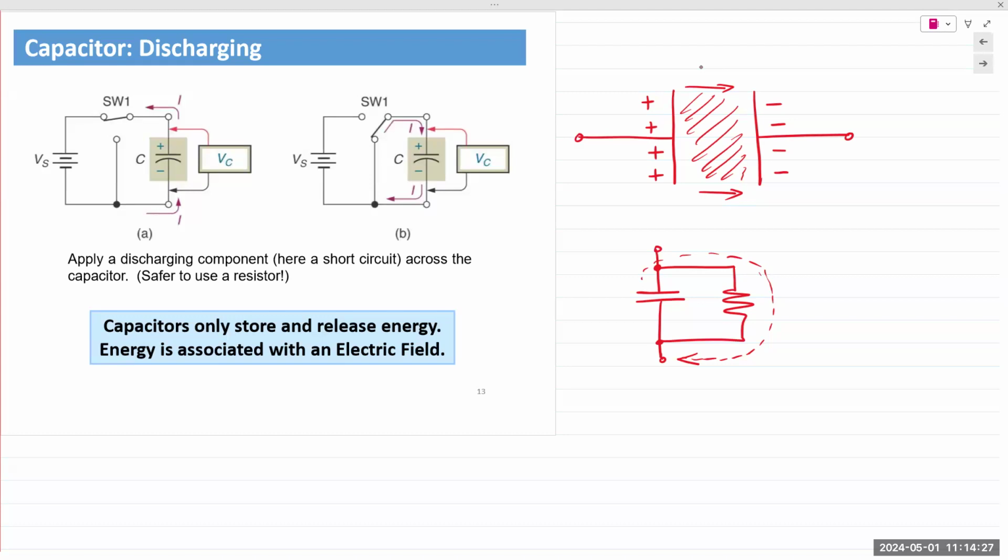What happened there was someone or a team was designing the batteries of this phone, and in the pursuit of thinner and thinner devices, they made the walls between the cells very thin. That led to a short circuit between the positive and the negative terminals of the cells. And so because it's a short circuit, R is 0, I is infinite. That energy is now being released. It's overheating. Obviously, when electrical energy is dissipated, it's dissipated in the form of heat, thermal energy. So it got hot. But it's not a capacitor, meaning the stored energy does not run out quickly. A battery has much more stored energy than a capacitor. And so the battery energy is still being released, for a long period of time. Heat is being built up with nowhere else to go, and it resulted in an explosion. That's what happens.